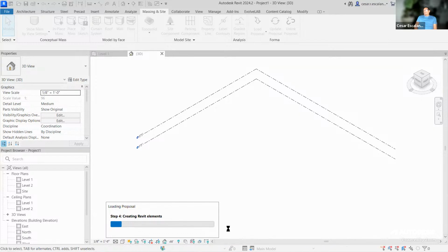And then the only thing you're left to do here is to define your project north, because the project will be oriented via the true north. The project north will be defined by the main orientation of either the architectural building or the adjacent street. You decide what the project north should be, and then that's a setup in the location bar of Revit.